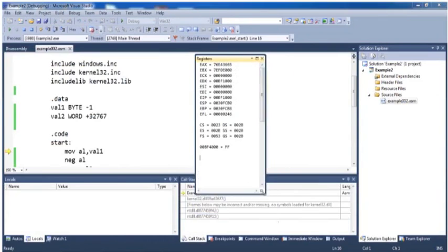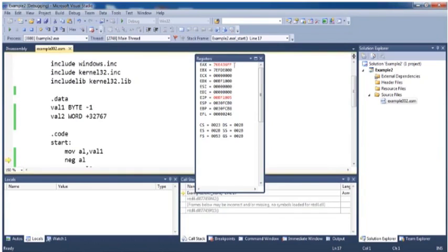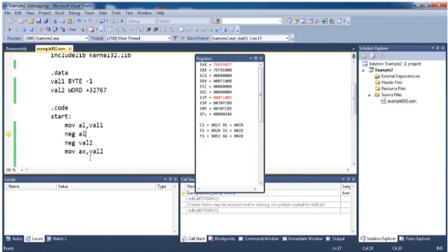Here you will observe the memory location. So here the first value, -1, is ff at 00bf40. So this will be moved to al. These two digits have been changed. And then if we move towards the next instruction, it is negate al. So if we negate al, it will be 01. So this is the negation. So al has been negated, it will become 01.